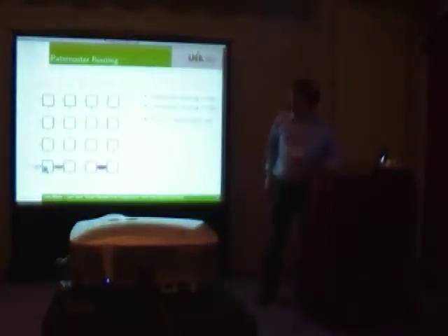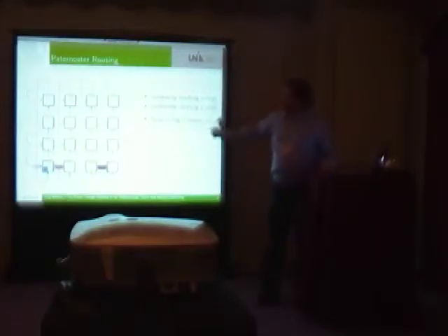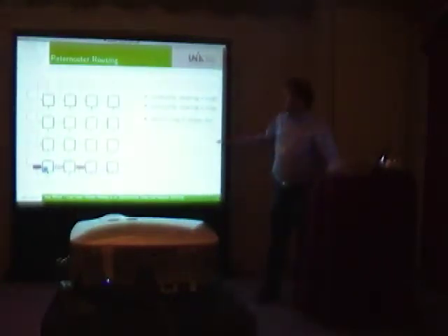So here's an example. We have this node, and we have a message here. It comes from the processing element. There is an injection, and now it has to wait for a free slot in this ring. So here's the free slot. And now it just has to wait until it arrives. Then the message is put into the ring, and it's transported in the x direction until it reaches its x destination.